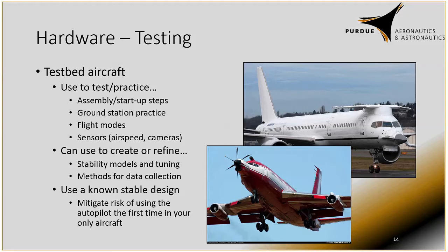It'd be very good for everybody to get a checklist and or a workflow for how you're going to get your plane ready for each flight. It can get you good on how to use the ground station, the different flight modes, either on the ground station or a RC transmitter, as well as your sensors. Know how your airspeed works, the cameras work, if you happen to use any external sensors, how to get all of that working before you're down to the time limit.